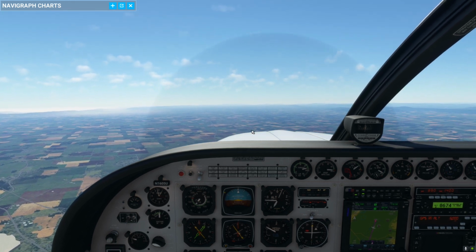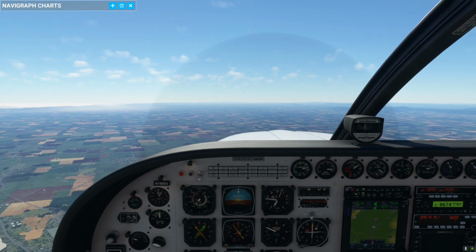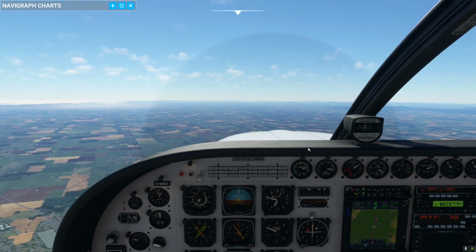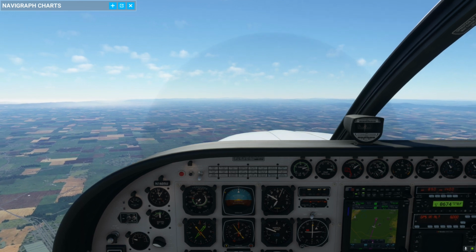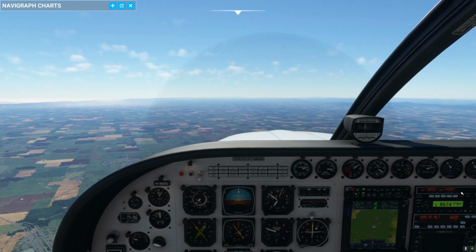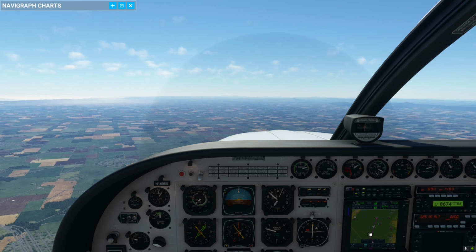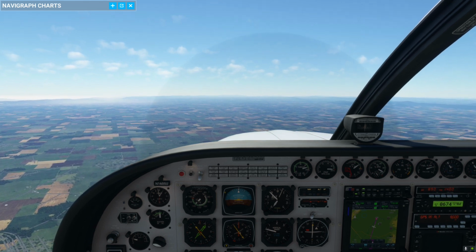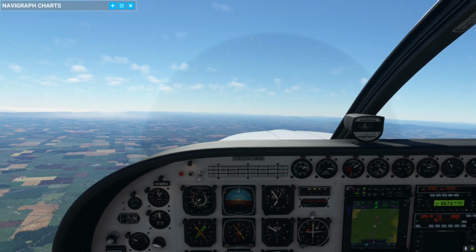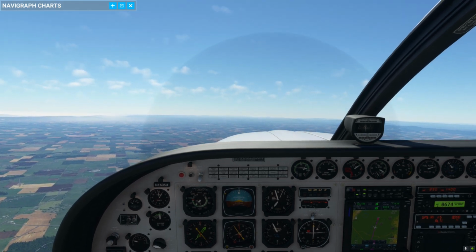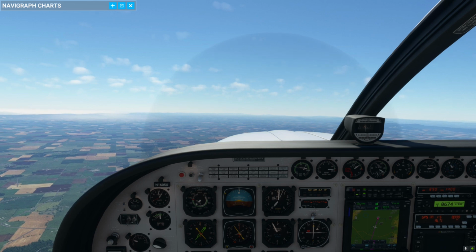Right, we're coming up on 6,000 feet. We'll pull back to our cruise settings here. Barley 01, climb and maintain 8,000 feet. Okay, climb and maintain 8,000 feet, Barley 01. So if you look over here on the autopilot, we're going to take that up to 8,000 feet. We're going to go VS again, vertical speed for the climb, and put our power back to climb power.